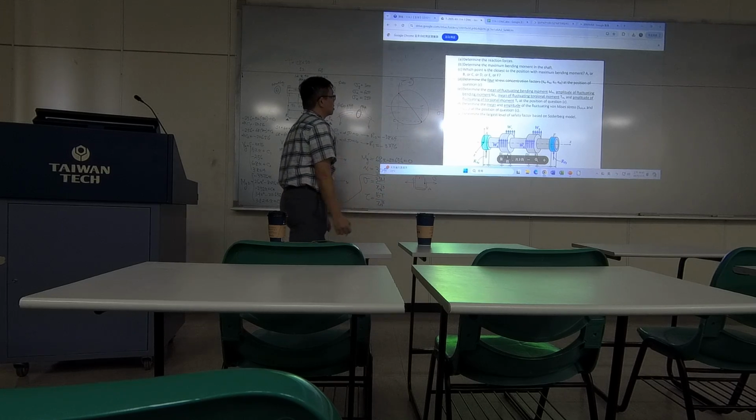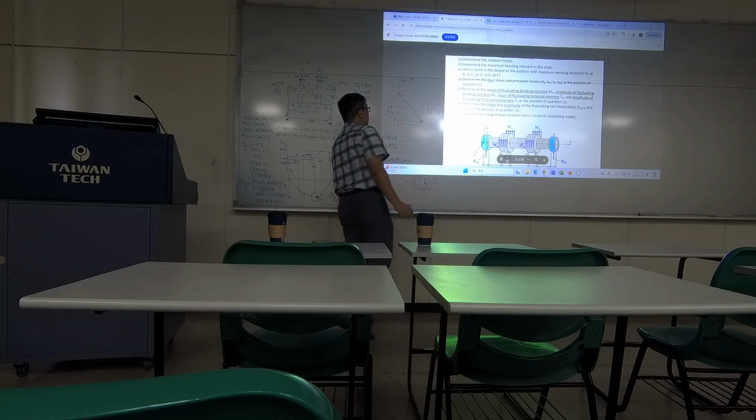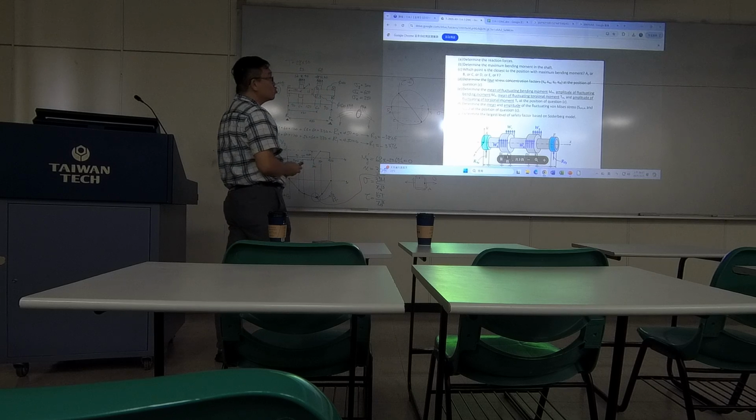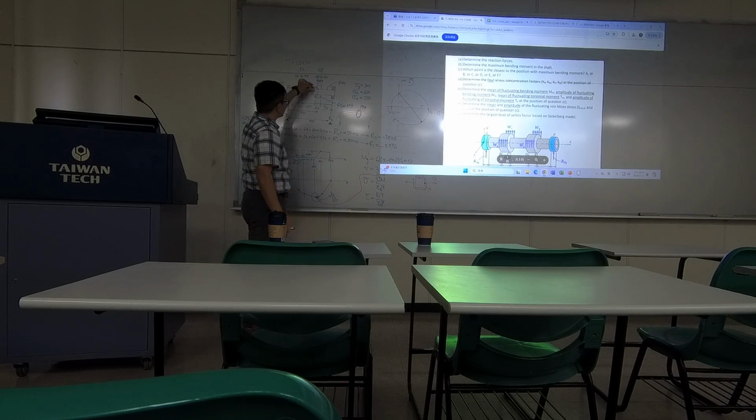So that's how you can draw a straight line and then form a circle. Okay? And over here, you can then compute the principal stresses, S1 and S2. So this is the Mohr circle for this particular point on the top. But when it goes to the bottom, it's a different scenario.